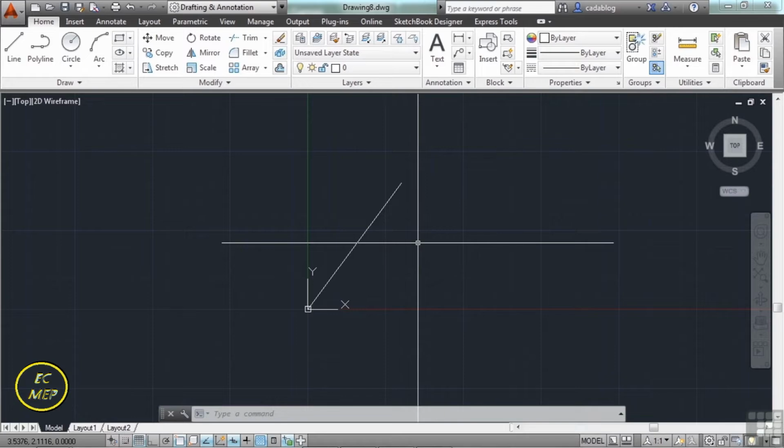And this is how surveyors will draw in AutoCAD. They will typically need to work on some sort of coordinate system. In the United States, we use a lot of state plane coordinate systems, and their origin is set at some arbitrary point in the real world. That's at 0, 0. And then they may go thousands of units away because they're usually covering large areas, and you can draw from point to point. So this is a very useful and just another way of drawing in AutoCAD.